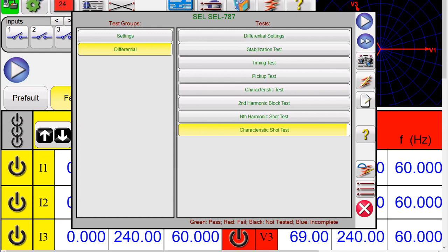For instance, you're mentioning here two IEC classifications, the 5P10 and 5P20. They are CTs that guarantee a 5% error up to 10 times the nominal secondary current in the case of the 5P10, and the 5P20 is 5% error up to 20 times the nominal secondary current. But there's no mention there, for example, of which of the, I think it's like 10 classes of VAs that you have on the IEC standard.